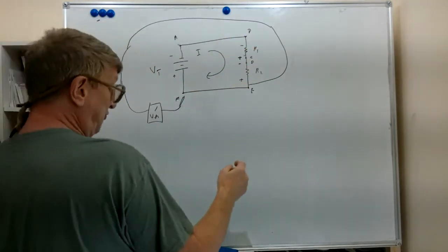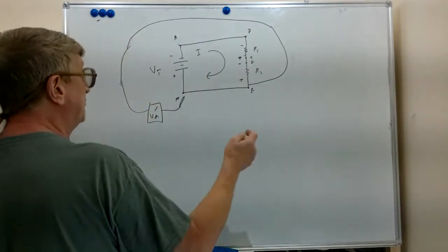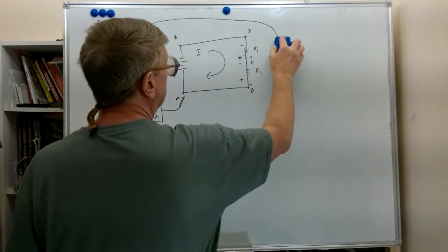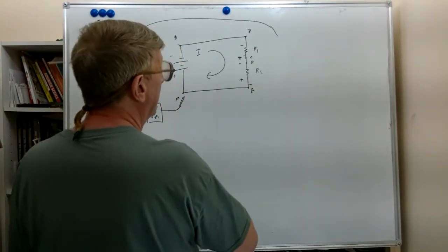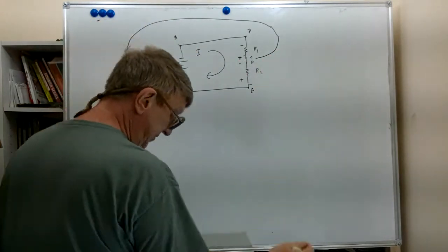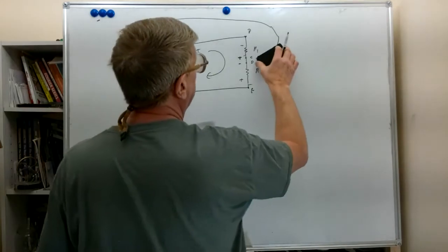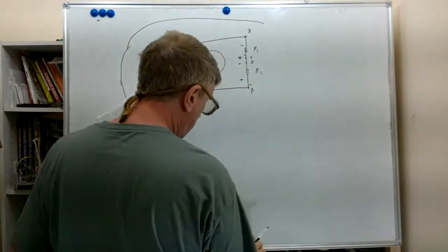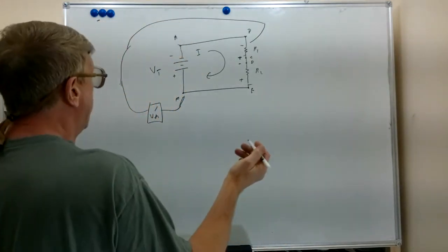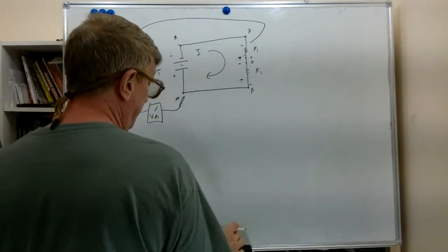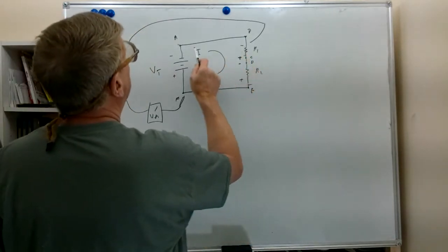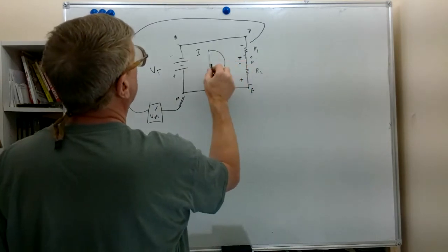If we went around the circuit the other direction with our meter, we would start here with very little, and as we moved up to here, taking readings, we would see it become a little more negative, a little less positive. Go up here, even more negative, and even a little bit less positive. And basically, the other thing you can see here is these polarities pretty well match up with the polarities of the source.